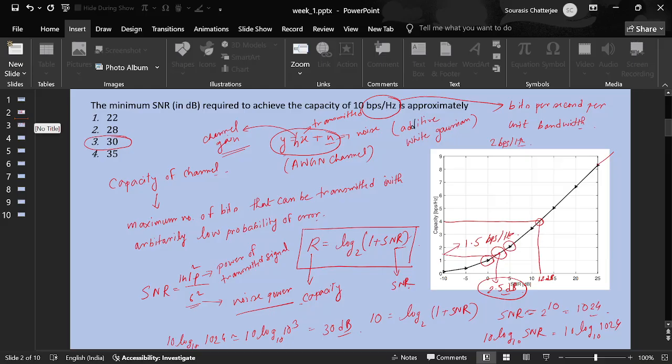I'm saying in terms of loss. Let's say I'm able to achieve 1 bps per hertz, or 2, or 3. What loss are we going to see in case we are not able to achieve the intermediate point? I guess my system is not going to be capacity achieving, right? For example, if my SNR is 2.5 dB, I cannot go to 2 bps per hertz, because that's the capacity when the SNR is 5 dB and mine is less.